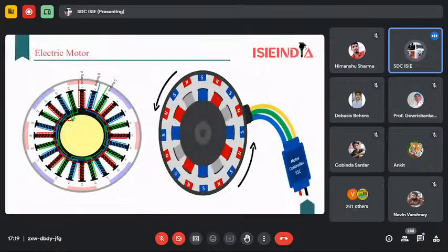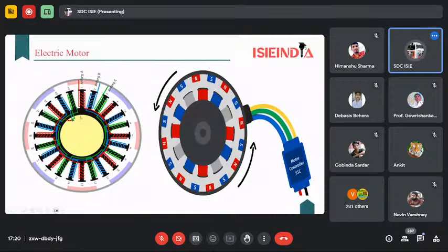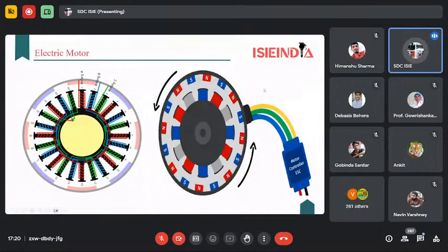So this is the circuit configuration, which we are going to see here, showing how the configurations are given to the stator part, which is at the center of the motor. You can see the animation showing how the polarities change in the stator part while the rotor magnets are fixed. According to the polarity interchange, the movement happens on the outer side of the motor. It is very easy to install in the tire, or we can say the wheel of the two-wheeler, so it is preferable for two-wheelers.